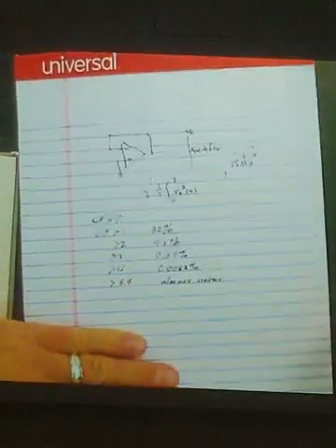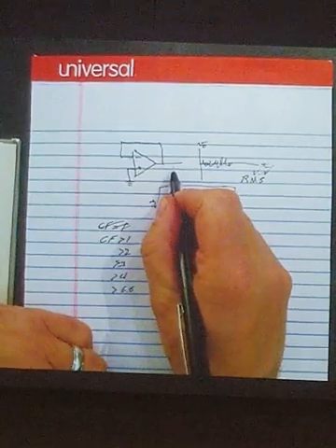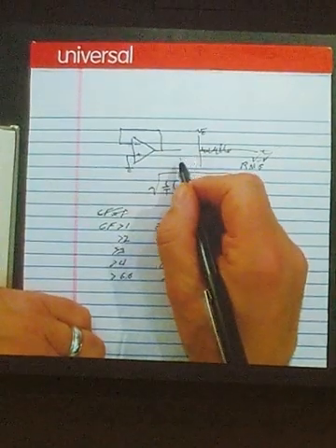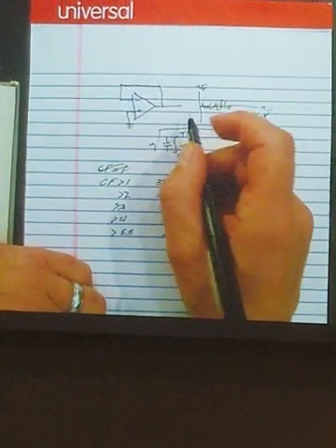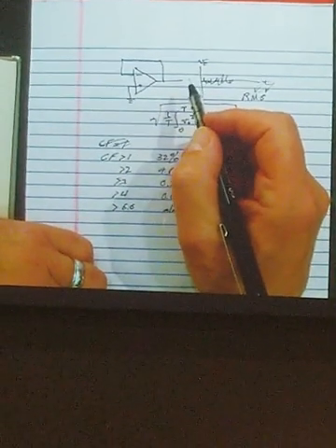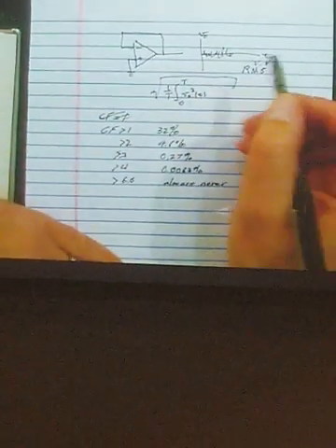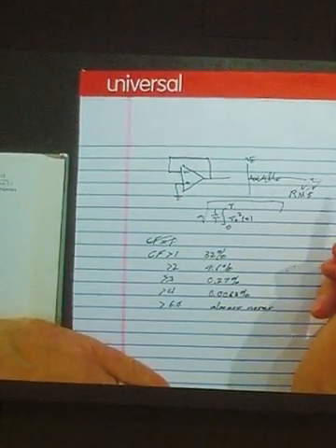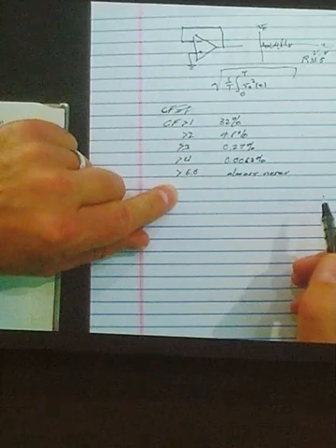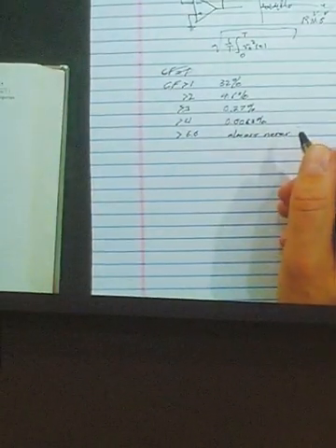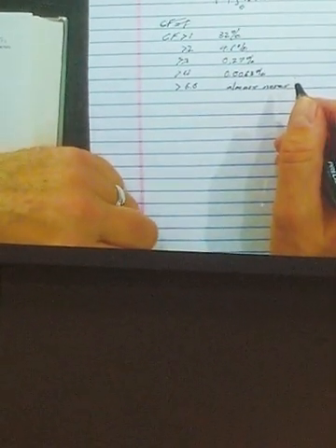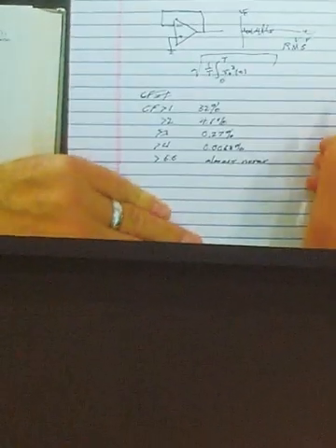So if you're running this signal into something that's nonlinear, where you're capturing these values, and again, let's say we have a 1 millivolt RMS noise, the probability that that exceeds 6.6 millivolts is almost zero. So if you're trying to capture an event that exceeds 6.6 millivolts, you're going to have to wait a long, long time for that to occur. And so we assume that the noise is basically bounded within that. And keep in mind, that's plus or minus 6.6 of the RMS value. So that's how we treat noise.